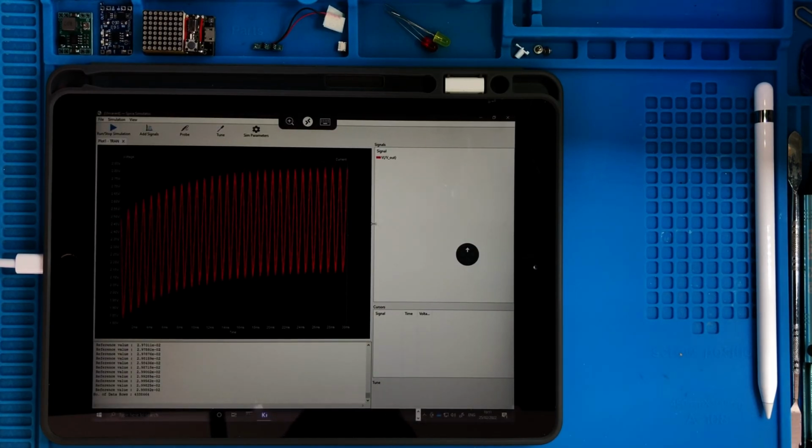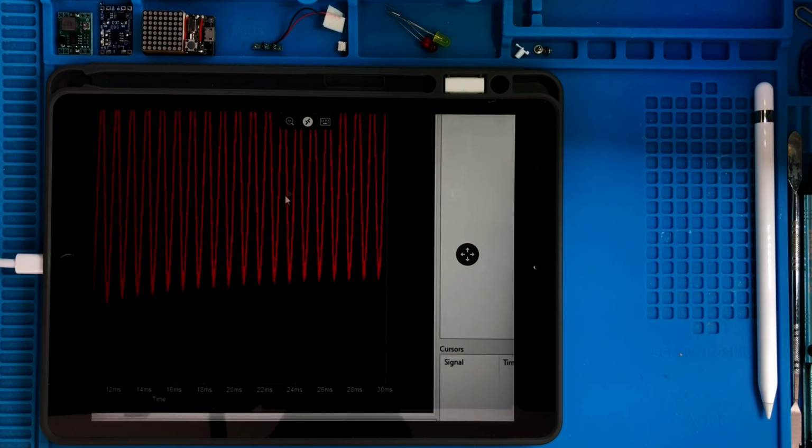So now you have a better idea of what's going on in the circuit. This transient time simulation is telling you another thing which is sometimes interesting, what is called the settling time of the circuit. You see that from this chart now the trend has been stabilized after, let's say, 20 milliseconds, 20-25 milliseconds.